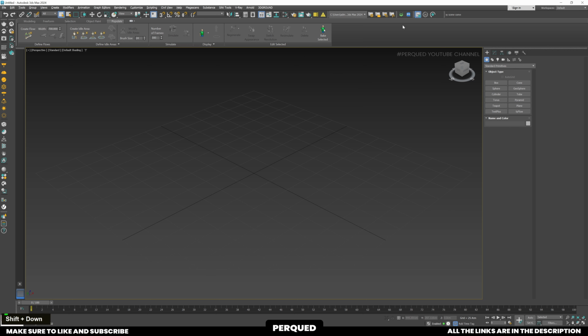These are the backup counters introduced by Autodesk in newer versions of 3ds Max. Previously, auto backups would sometimes occur while users were working on important or heavy tasks. In large scenes, 3ds Max would automatically create backups, which occasionally caused crashes. To address this issue, 3ds Max introduced the backup countdown feature. This countdown shows when a backup is about to happen, and if you're in the middle of important work, you can reset the timer from here.